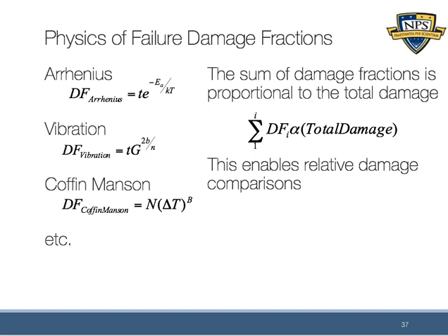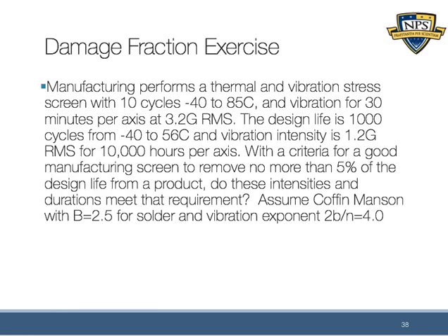One point to make here, and this is a note for the homework, is that this does not predict the life of the component. It may have that flavor to it because we're talking about lifetime, number of cycles in a lifetime, but we have to be careful using these to predict the lifetime, especially when we're looking at vibration mixed with temperature. It can get a little dicey. So I just want to make a note of that. It's not to predict the lifetime. Let's do one final example in this lecture, which is the exercise for damage fraction.